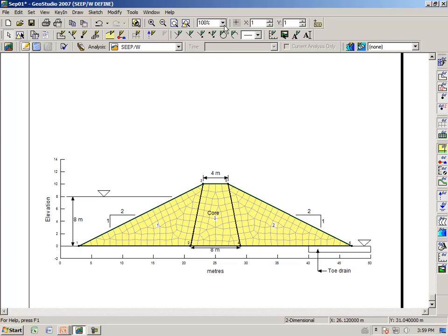So once again, when you are zooming in at 100%, the true scale, then you should be able to see all the elements. And this brings up a point: the scale should be the same in the vertical and horizontal directions. If you are at 100% and you cannot see the elements, and it simply turns into a solid black area, then I would suggest to you that you have way too many elements and nodes. So there is a very rough guideline for you in what is an appropriate mesh.